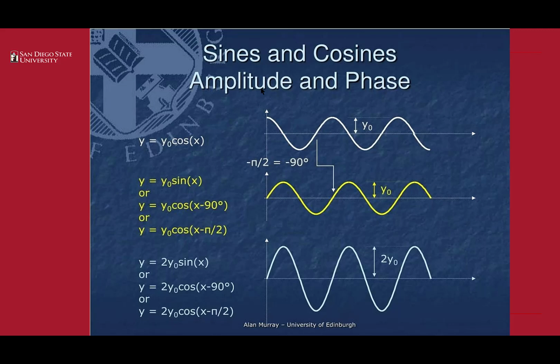So if you look at the vertical axis, we can see that the peaks of the signals are 2 times larger. Actually, if we consider the negative part, the difference becomes even bigger. But when we are measuring this amplitude, we always use the distance from the x-axis to the peak on the y-axis. And this is how we represent the amplitude. We are not measuring the distance from peak to peak, but 0 to peak. And again, here, by changing the amplitude, we did not alter the frequency nor the phase of the signal.